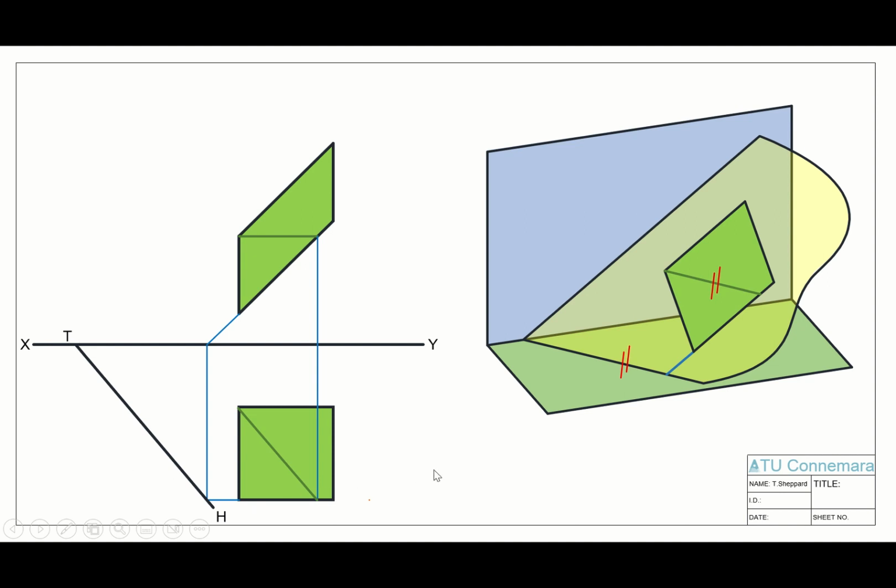To find the vertical trace, we're going to continue this watermark approach by drawing our parallel line from any point on the lamina until it meets the vertical plane, giving us the vertical trace. So in this example here, there is our point I'm going to pick, the top point up here, this point here in plan view, and our watermark is going to look parallel to our horizontal trace, parallel to our strike line or our trace line here, and there is our line like that. And I extend it on until it meets the back wall.